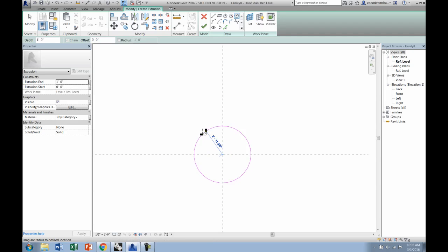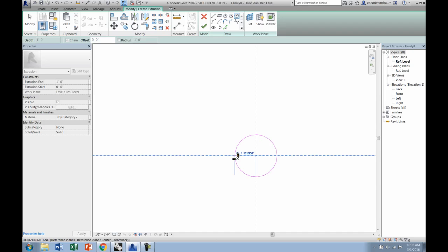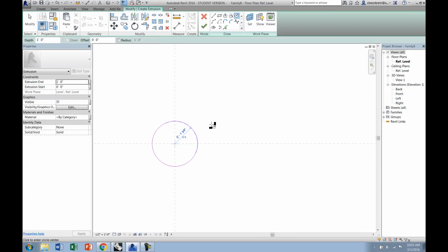And you can start off with, say, a 2-inch. Let's go with 3.5. And then we'll do a line through here, and then offset that line, say 1 inch. We can do a circle in the center. Make it half. And now we'll just do some trimming and extending. So there to there. There to there.